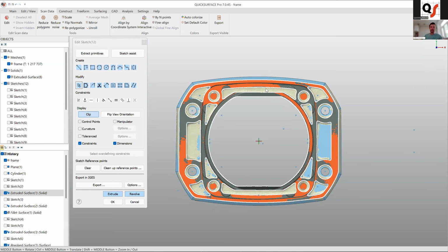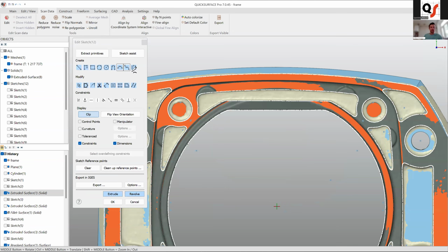Even if you are creating some geometries, if you are pulling some lines somewhere, for example, if we're creating an arc here and you are trying to pull it further, you can see it starts to snap in some locations, and if you have more entities in your sketch, it can try to snap to your different entities. So at the same moment, you can mess up everything pretty quickly, and later you can not spot this at the same moment, and you will have some problems later.